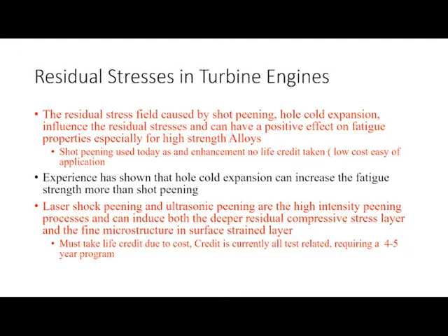We know that, and they are especially valuable on high strength alloys. I will tell you, shot peening is used today as an enhancement, what I would phrase as a durability enhancement, but there is no life credit taken in a turbine engine application.